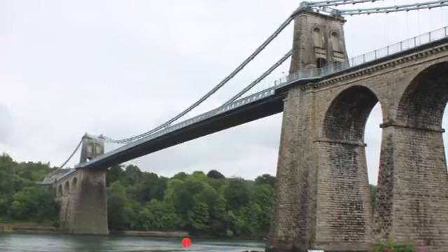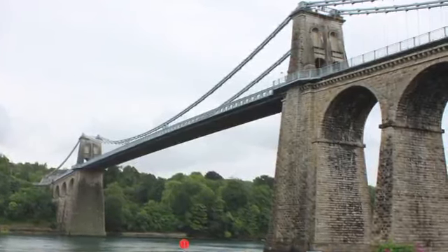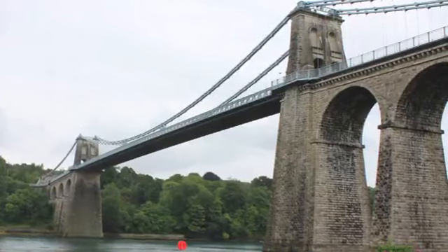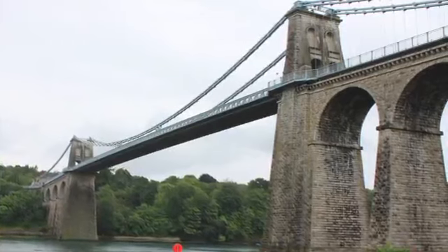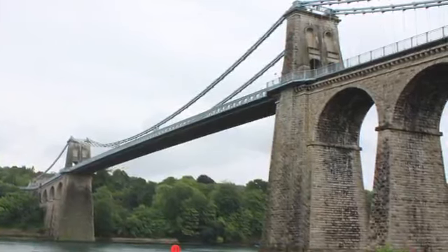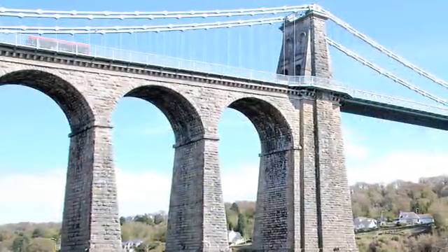If we look at the side spans of this bridge, we see that it has both arches and suspenders. And this again is ambiguous. It doesn't tell you clearly how those loads are being carried. But Telford did this because he was concerned about wind. He wanted to make sure the back spans were heavy and anchored.